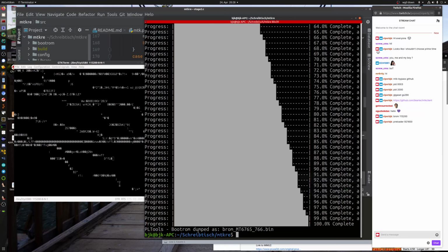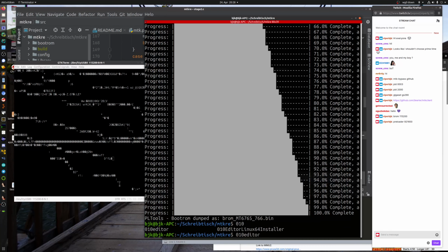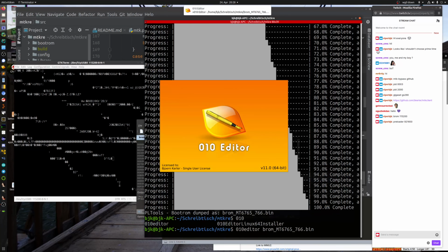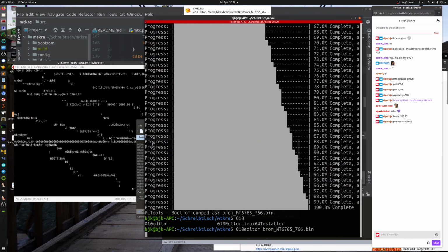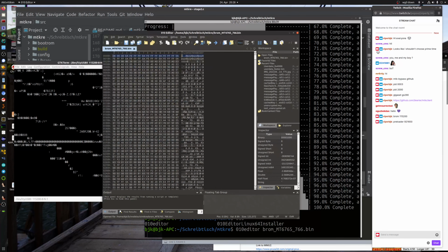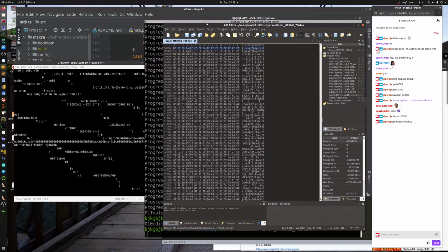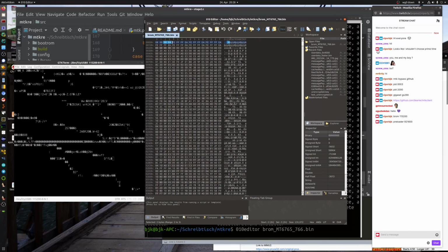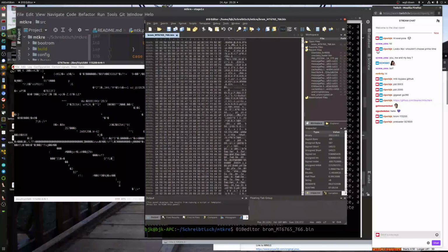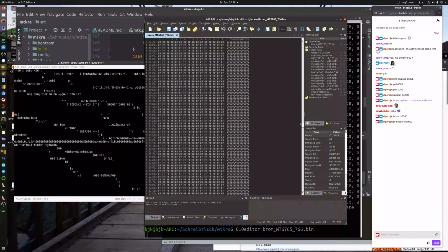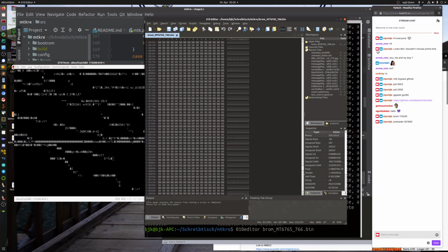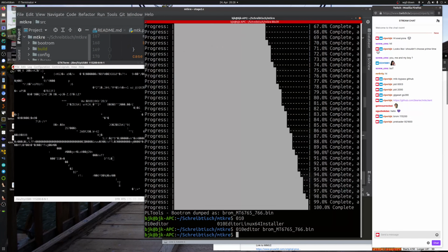So as you can see, we've dumped the Bootrom. Just to make sure that we really have dumped the Bootrom, because sometimes it's empty, we're just going to open it up. And as you can see over here, we've got some fancy EAs, which is typical opcode for ARM architecture, and it looks pretty good. So yes, that's clearly a Bootrom of MTK. So that's the ROM view's code.